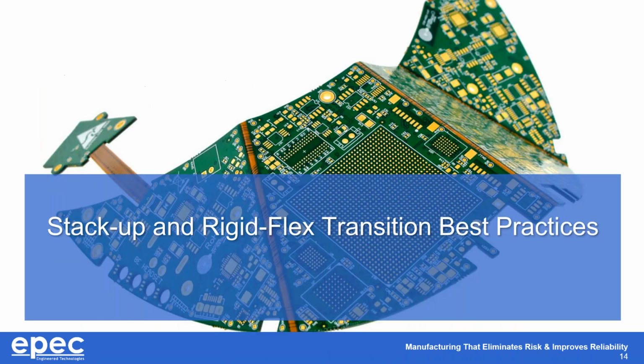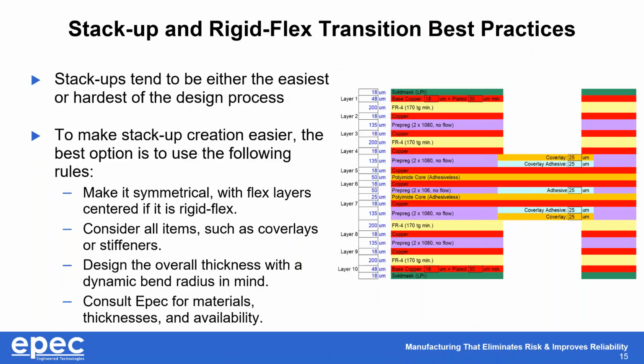Moving on, we've got stack up and rigid flex transition best practices. Stack ups will ultimately almost always end up being either the easiest or the hardest part. What I mean by that is a simpler design will obviously have an easy stack up. A 1-layer design will have an easy stack up compared to this 10-layer design that I have here on the side, where it's an expressly more difficult stack up, and where if you don't know manufacturing, then you might not know how to lay up the stack up as shown.